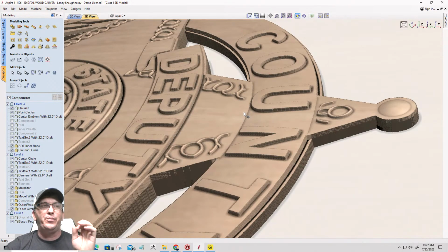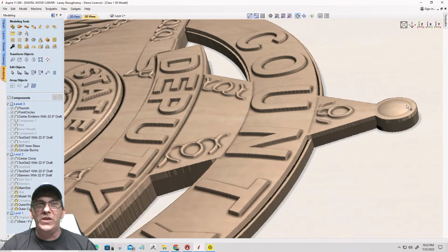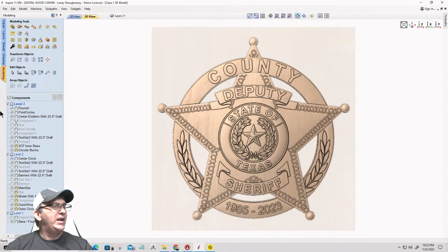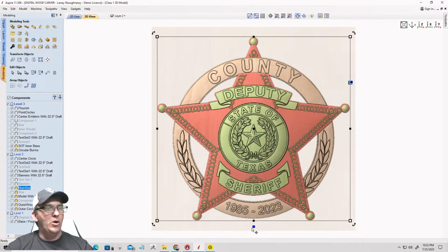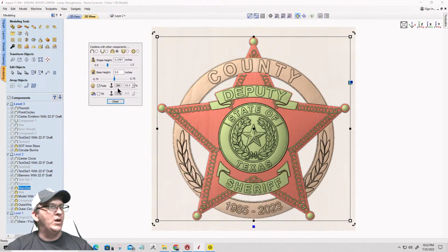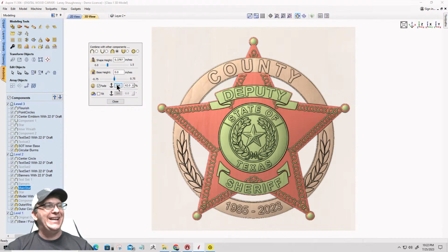But over here, it has not started to quite fade properly, because the fade really didn't begin till probably somewhere around here in the middle. Remember, our first click was here and our second click was up here. So we're going to redo that. We're going to turn this back up. We're going to go back into that main star tool and select it and open up the properties of that star again. And on the fade, we're going to reset it. So we're going to click on set again.